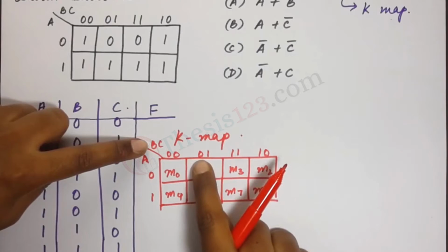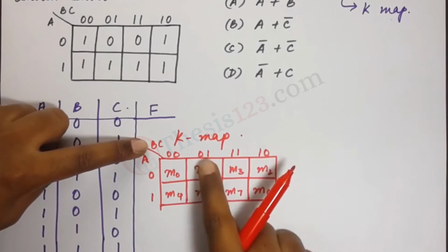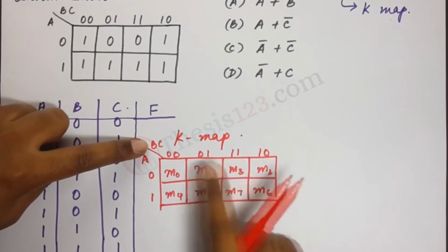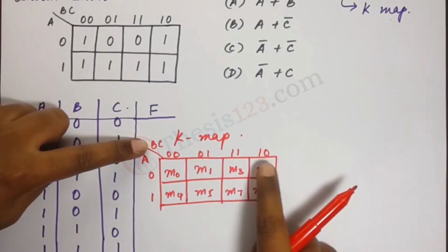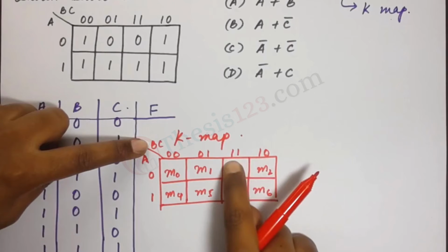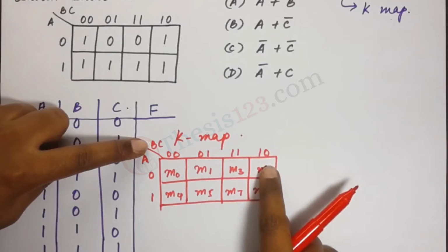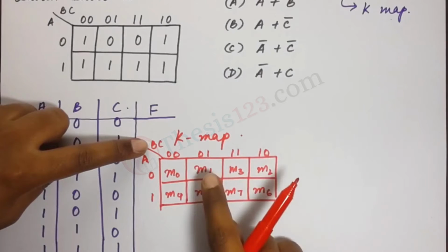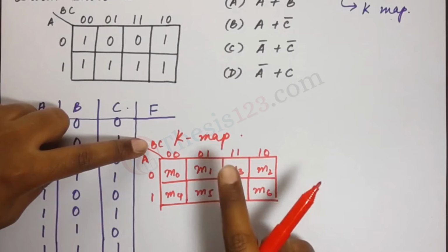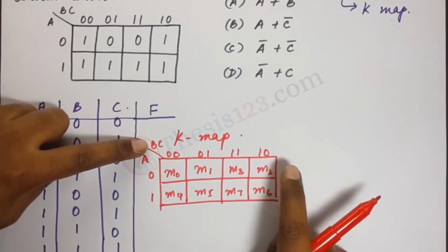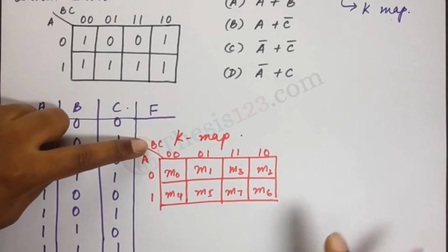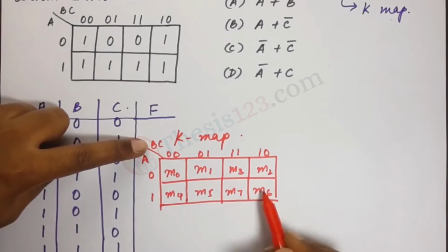You will notice that only the value for B is changing from 0 to 1, while C remains the same. Now if we were to place 1, 0 here, you would notice that both B and C are changing. We don't want that. There shouldn't be a change in both B and C. There should be just one changing. That's the reason they are arranged this way.